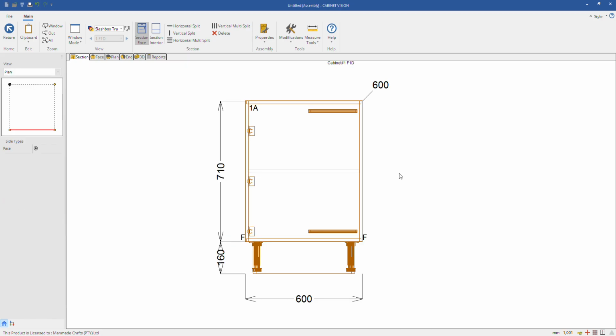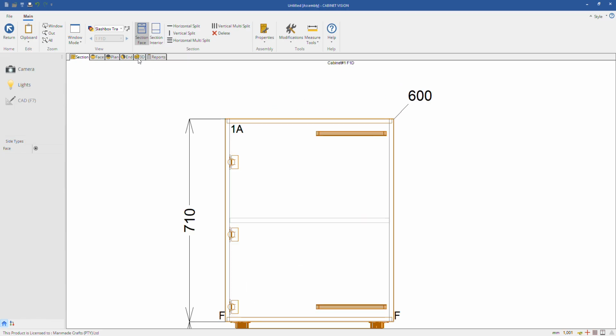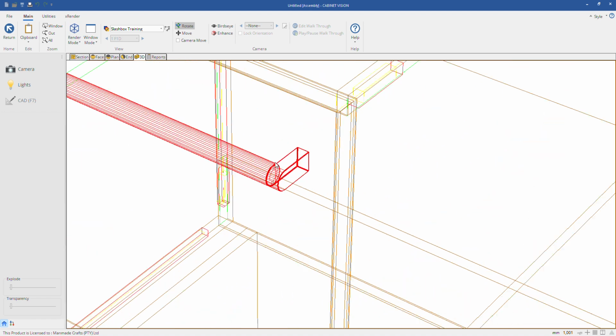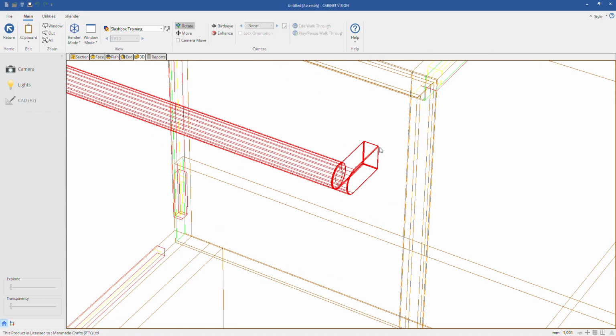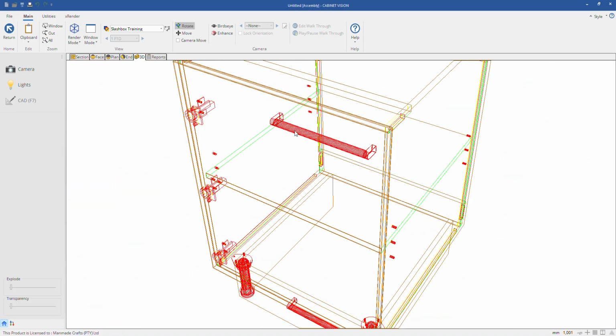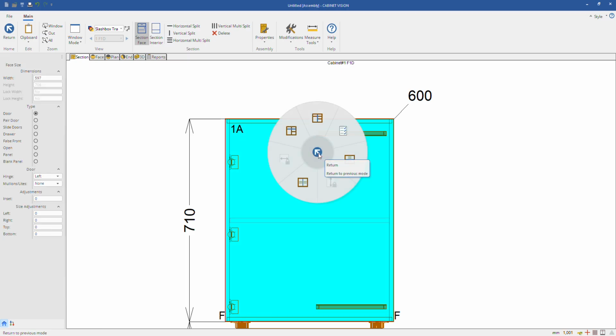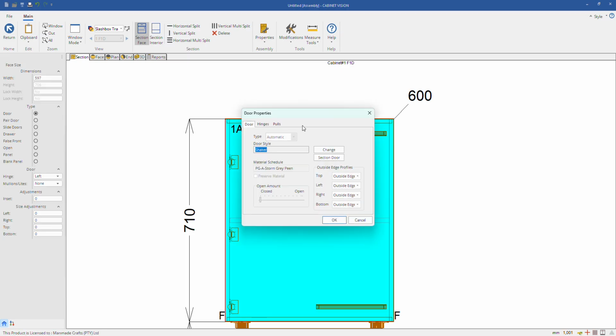So for machining purposes, would that come through as well if you add the holes on the model? Right. On the doors, yes, on the handles. But the handles that I created do not have holes. The reason for this is because not every client drills the same pilot hole depth or width. And you might drill it and find you don't have stock of those handles and you're stuck. Correct. So that's the door properties options that we can modify and change there.